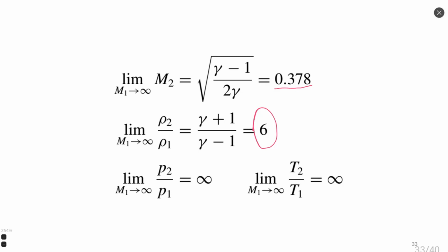And second, if you try to add more and more energy into the flow, you can have another physical process of transformation, for example, ionization or dissociation of gases, which would consume most of this energy. So because of these 2 reasons, Mach number can never be infinite or very high. I would like to remind you that for hypersonic flow, a typical value is something like Mach 25.